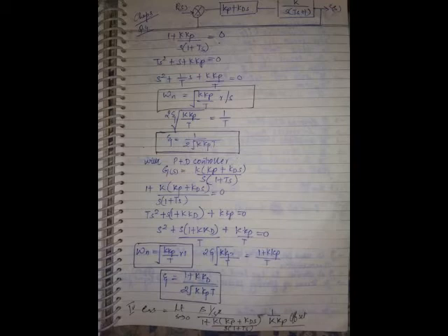So when you use a PD controller with any plant, you have to observe its effect only on the improvement of speed of response. And whatever error it is going to keep in the system, that error should be acceptable in that application. Otherwise you can't use it. So generally, in systems with large time constants, like boilers, or where transportation lag or dead time effects are very large, we use these controllers only to improve what? Speed of response. You understand?